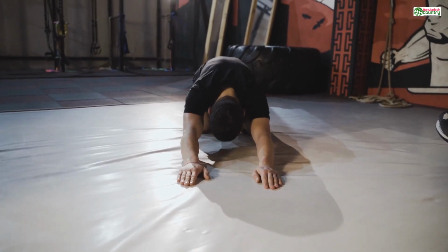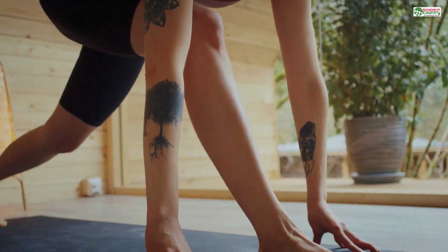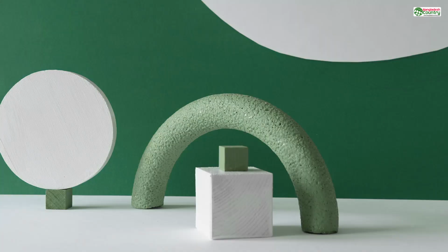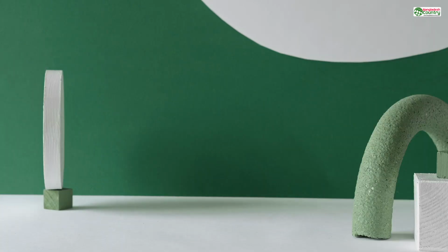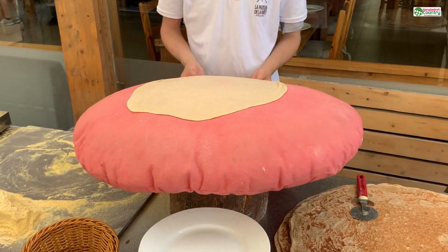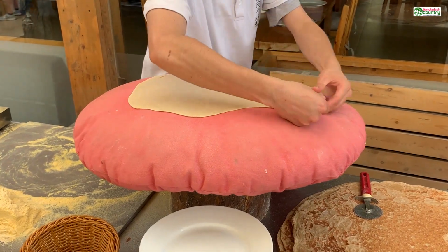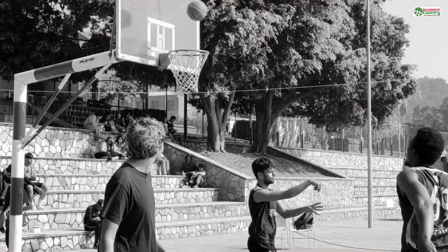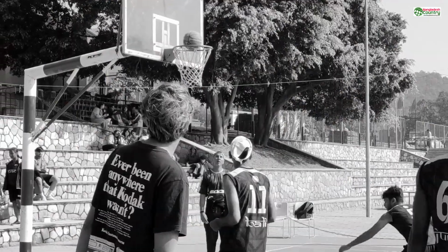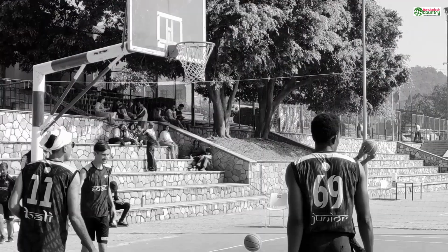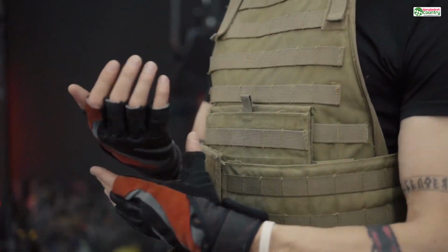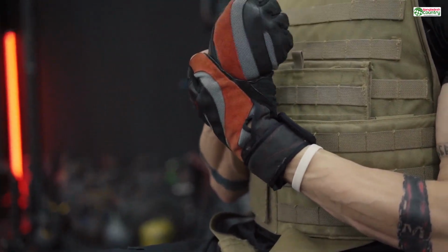Many forms of PETG are also considered food safe, making it a popular choice for things like cookie cutters or custom kitchen containers, though you must always verify the specific materials certification with your printing service. It's like the material used for water bottles: tough, resilient, and slightly flexible. If you're not sure what to pick and your part needs to be reasonably strong, PETG is often the safest and most versatile bet. Finally, in the world of high-performance plastics, there's nylon.